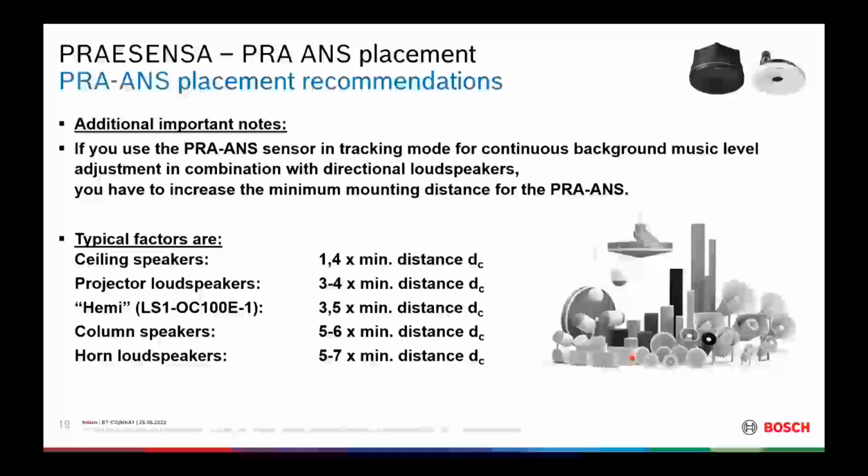Yeah, a good practice could be, if you commission a system, and in most cases you do this in a quiet situation. We all know that sound system commissioning, because of tuning the system and measuring things, you do not want to have other noise sources. So normally you do this at night, like in my example of an airport terminal. If everything is empty, you are there at night, and you may test your system, tune the system, level the system, etc. So you start with the silent situation.